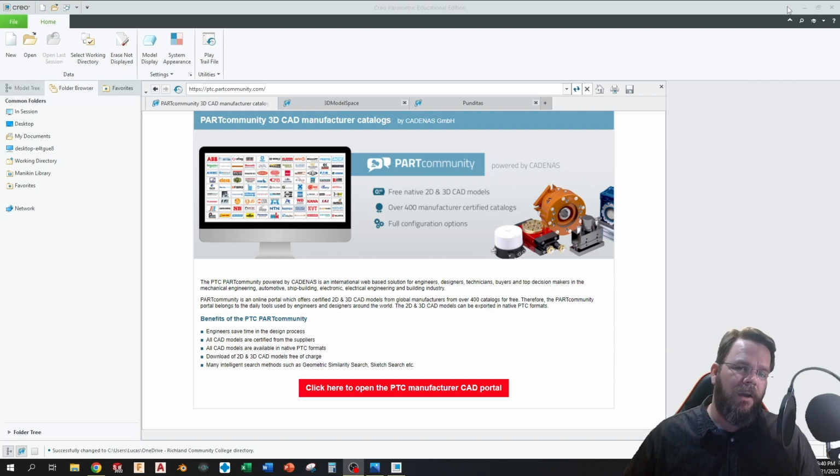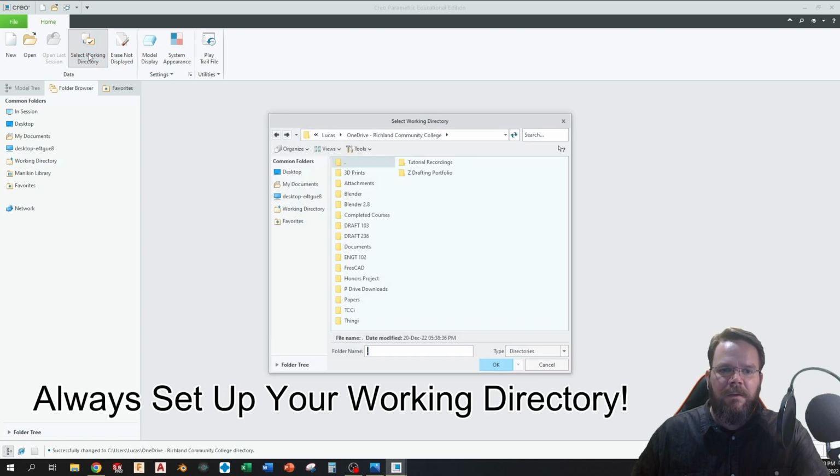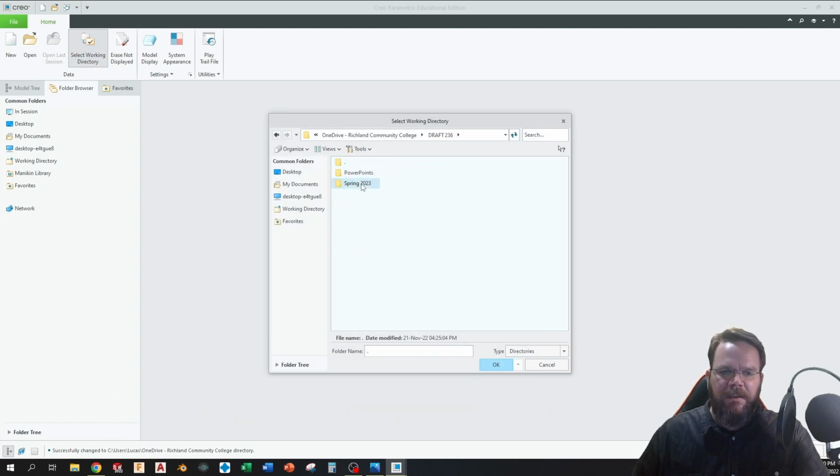All right, so now that we know the basic steps that we're going to be taking, let's go ahead and just get into it. So I've got Creo open here. Now with Creo, if you watched the last video, the very first thing that you're going to do when you open Creo is you want to go up here to select working directory. And here you want to navigate to whatever folder it is that you want to keep your projects in.